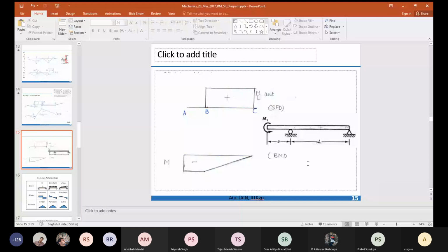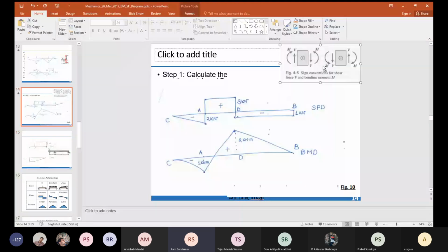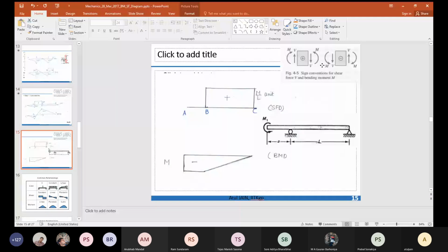So this is only the third load. These are the only three types of load, and perhaps bending moment is actually the simplest. You only have to be careful whether it is positive or negative. But practically, how do you apply a bending moment without applying a shear force? Let me show you in the next slide. Since it is in this phase, this is positive. So the reactions will be, this is actually a negative bending moment that has been applied. So this is minus.